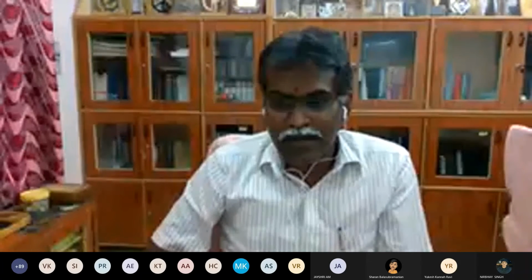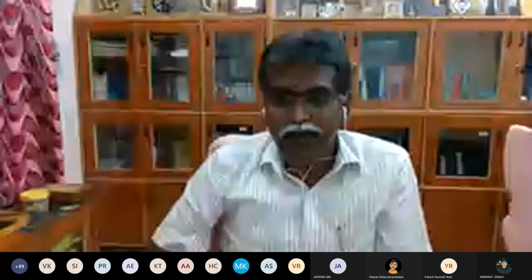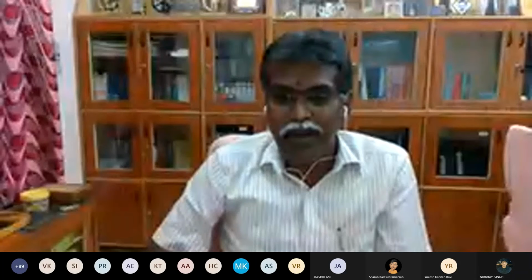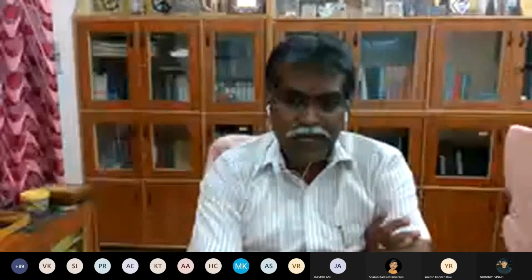Please make a note on that as number one. If I have a glass of water that is certified good in all quality, but has some turbidity, people may not take it because of its aesthetically displeasing appearance. Turbidity may not be a health problem, but it will create aesthetically displeasing opaqueness or milky coloration in appearance.